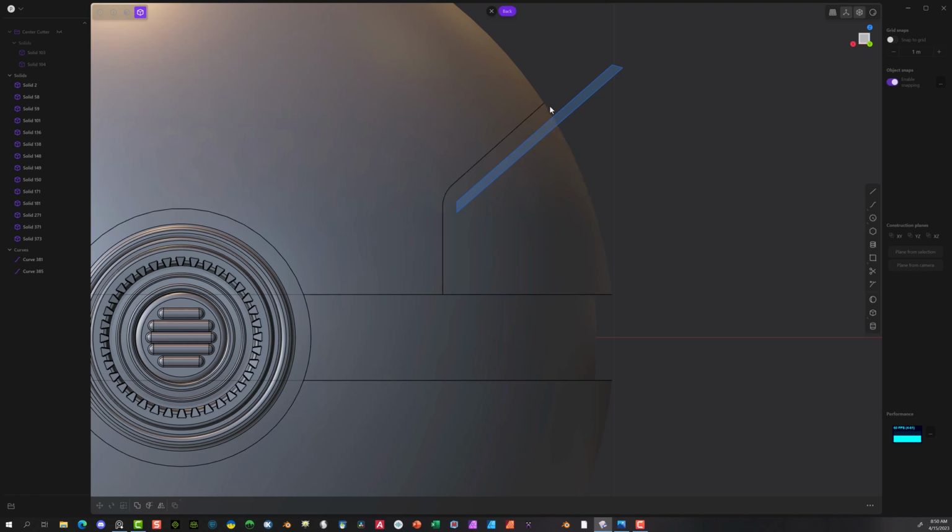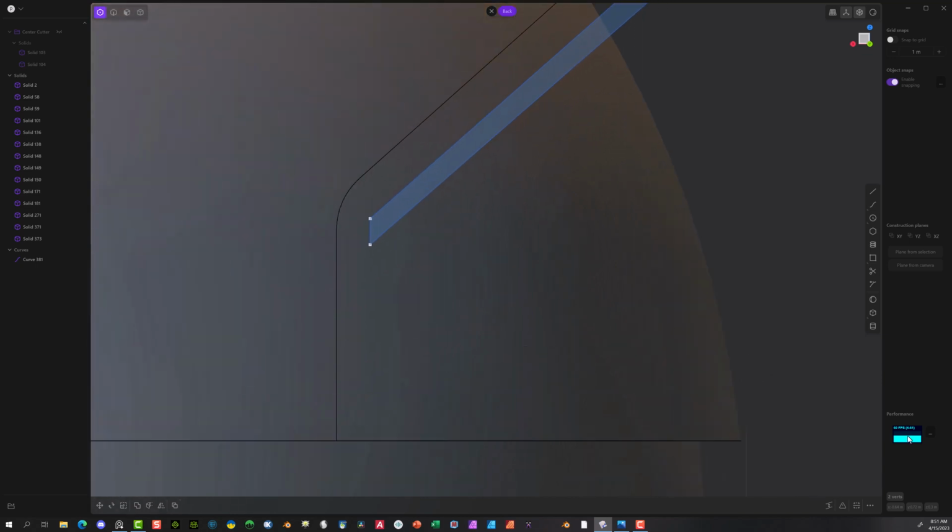Alright, so let's go ahead and hit the edge tool again. Select this, hit shift key, say J key to join them. Now we're going to hit the points. Again, I don't want it too sharp. Just going to hit the fillet. This becomes sometimes a little tough at this distance, especially if they're sharp. So if you can't really get it to work, say escape, I would suggest getting closer to it or do one at a time.